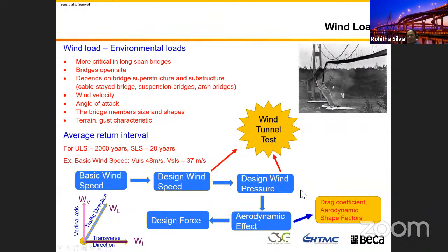I'm not going to go into detail with those. This design force we can calculate three-dimensionally. It could be longitudinal or transverse. The transverse is normally significant, because bridges are longitudinally quite long and you have a barrier. Your superstructure's total depth is sometimes close to 3 to 4 meters, in general about 3 meters. So there's a massive horizontal force acting laterally on your bridge superstructure.